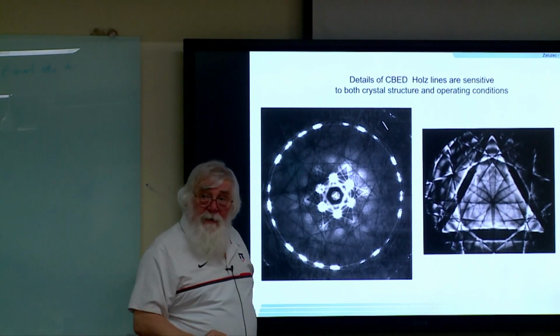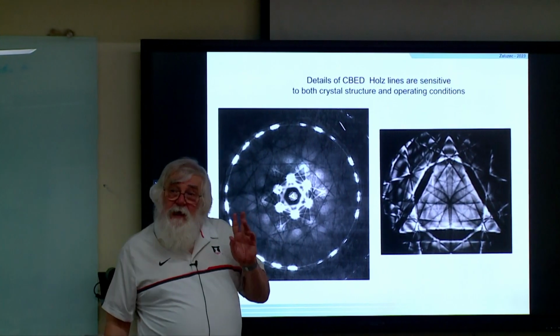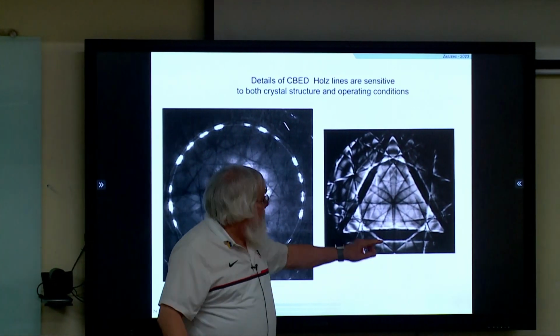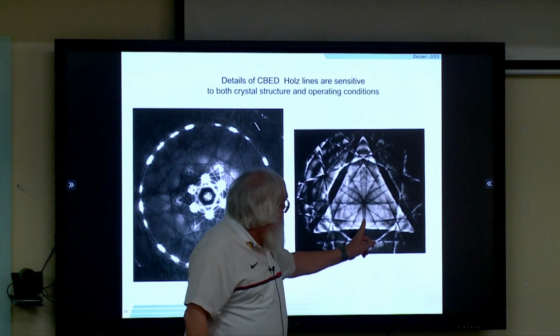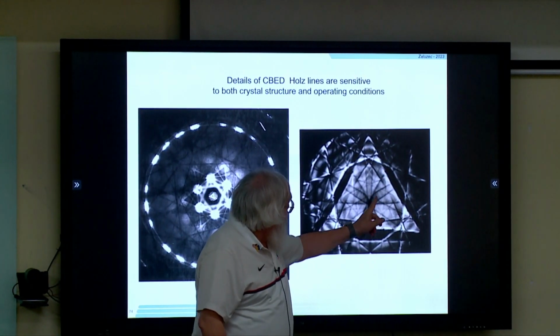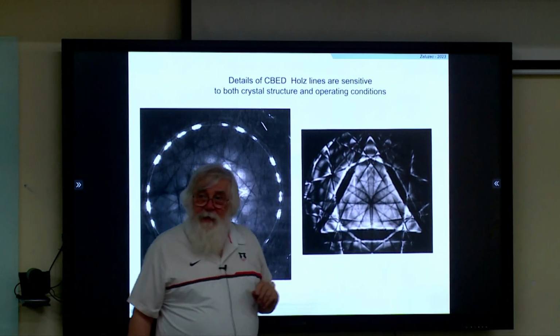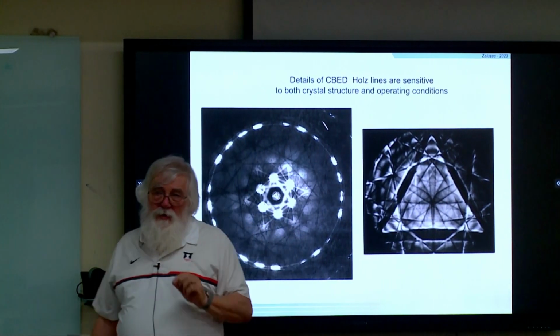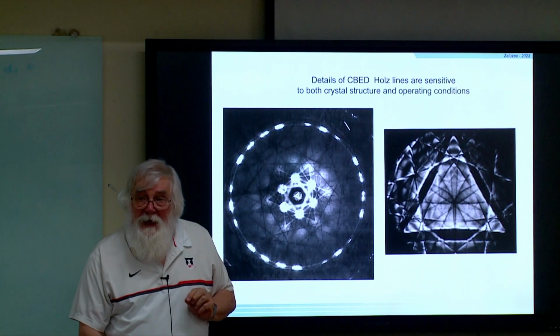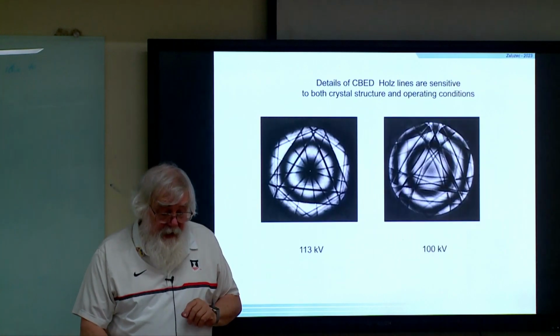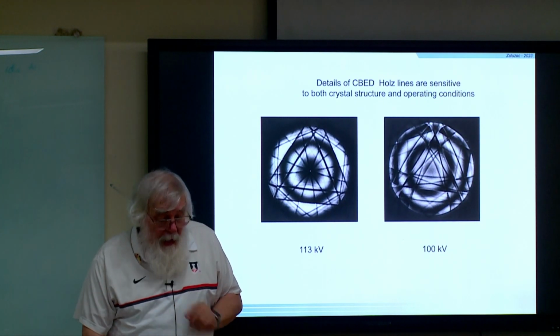It's twofold symmetric, close to threefold. And what's happening here? We've got a distortion of the lattice, just slightly. If it was perfectly symmetric, this axis would look exactly like these two. So it's a very slight distortion, so very small changes in lattice parameters can be detected using this technique. And again, I'm going to leave that to Hamish because I'm getting tired of talking.